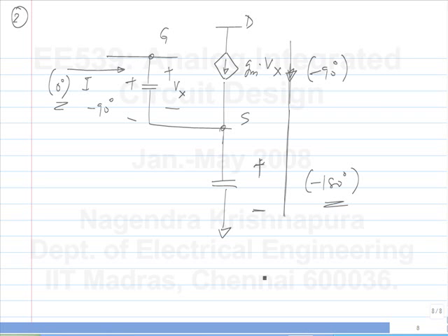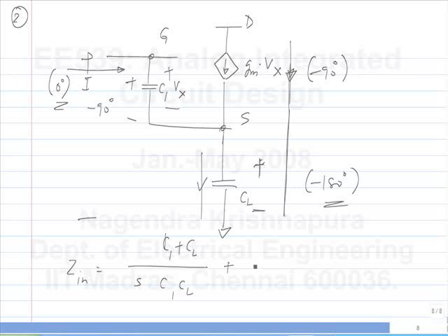So that's what gives you out of phase voltage or a negative resistance. Of course, that's not the only current flowing through this, and that is not the total voltage that appears at the output, but that's part of it. So that gives you a negative resistance. And if you do the analysis, it turns out to be, if I call this C1 and CL, this I will give you a voltage 1 over SC1.